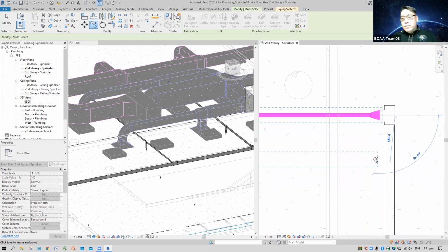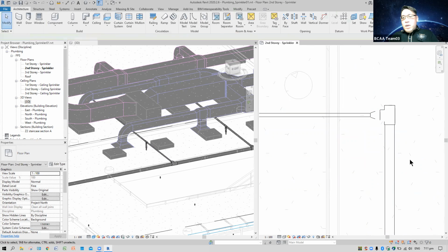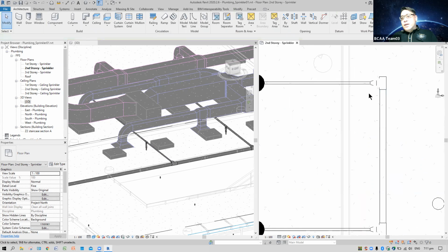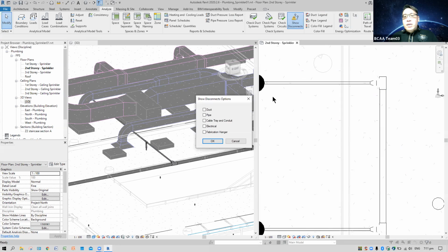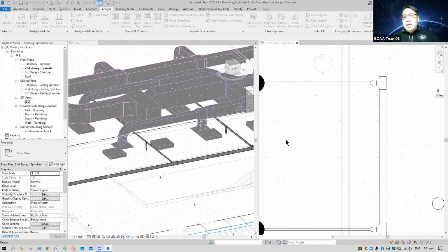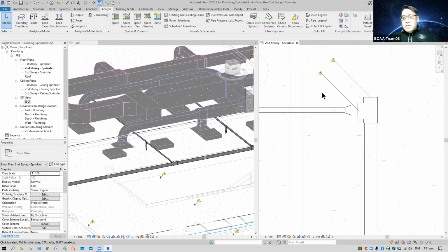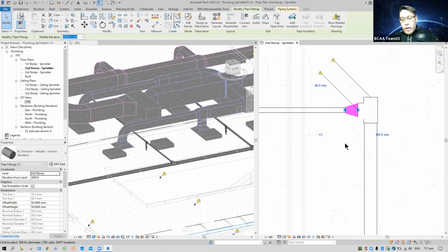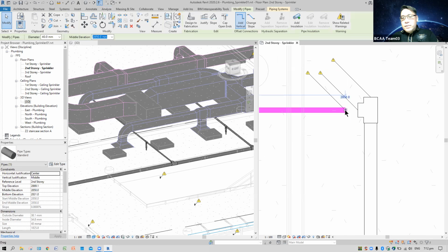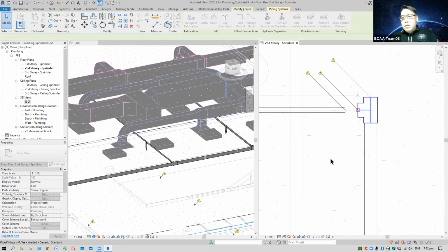But you notice something? Let me show you. Normally when you copy this way, when you show like this, it means the connection is not properly connected. If I go to Analyze to check the pipe connection, right? Confirm it is telling me this has a leak. It's like that. So how? Don't worry. This part I delete away. Select this. Drag.